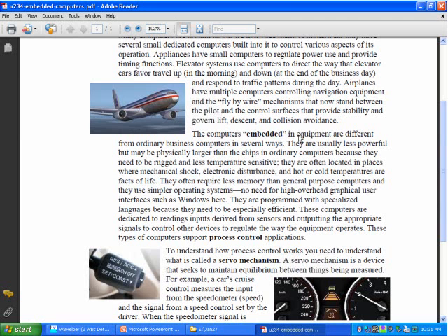Now, in ordinary operation, what fly-by-wire does is the pilot may give the main input to the computer, which is the direction the airplane is going to fly, and the computer, by way of reading the sensors indicating variations in air pressure and the way that the airplane is moving, may smooth out the whole turn, may smooth out the ride of the aircraft, so that it's assisting in the control of the surfaces of the aircraft, making for a better trip in the airplane, basically, and more control over the aircraft. Well, that kind of computer is an embedded computer.